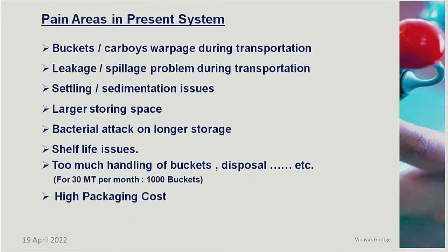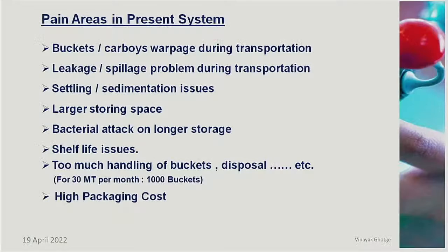because the buckets need larger storing space for storage. Bacterial attack on longer storage, especially in the high temperature ambient conditions, the bacterial attack is quite fast. And shelf life issues. In the sense, normally most of the water-based coatings have about 6 months shelf life, but in case of ambient conditions, very high temperatures, the bacterial attack can be even faster. Too much of handling of the buckets.